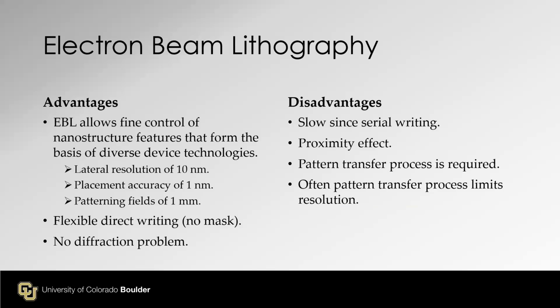Of course, EBL has advantages and some disadvantages. EBL allows fine control of nanostructures. These are typical numbers: lateral resolution of 10 nanometers or better, placement accuracy of 1 nanometer, pattern field of 1 millimeter. This is for a dedicated E-beam writer system.